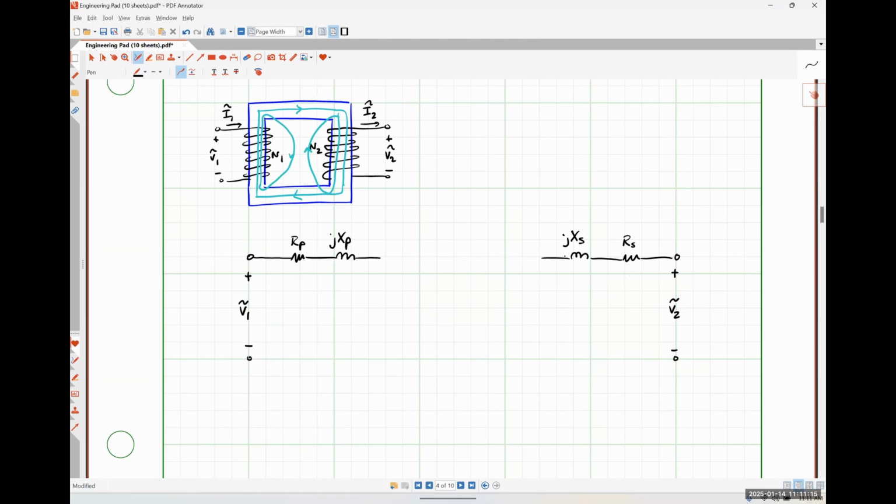So I'm going to choose to represent that as some resistance here that I'm going to call R sub C, okay? This resistance is placed in parallel, or in shunt, across the terminals of our winding because the value of these losses is dependent on the amount of applied voltage, okay? So it needs to be in parallel so that it takes into account that total voltage.